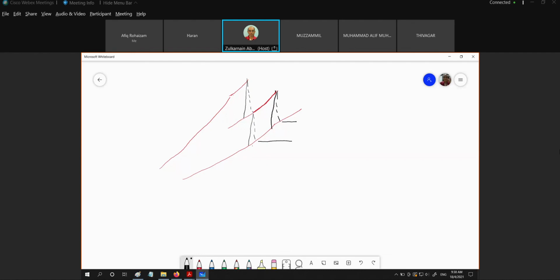The first thing I want to show here is the temperature difference between with reheat and without reheat. With the reheat process, the exhaust gas rejected from the plant is higher compared to without any reheat. And what we are going to do is make use of this energy content in the exhaust gas to heat up the air after the compression process.